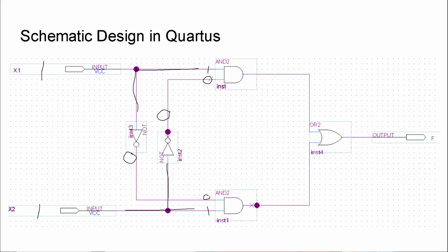So this is a true and a false, a false and a true. And like I said, we've got a false and a true at the AND gate. That's false. The AND gate is looking for two of the same. That is false. The OR gate is looking for simply one true. We've got a 0 and a 0. That's false, so our output is now false, or 0.